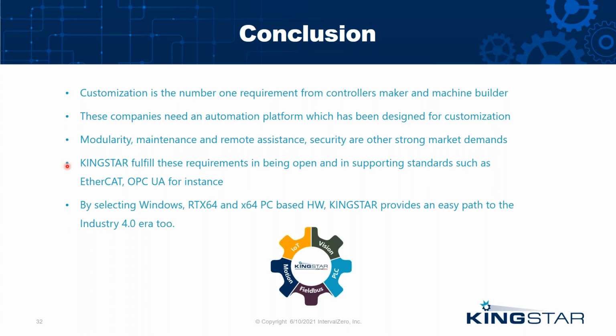The next important piece is the communication between the different functions, the different modules inside the machine, and between the machine and other machines, other hardware. There are now standard and open protocols to do this. The ones we believe are the best suited are EtherCAT and OPC UA, because they are very standard, they are open to many different vendors, many different hardware vendors, machine vendors use them. So you will be able to find the products you need, the interfaces you need in these protocols.